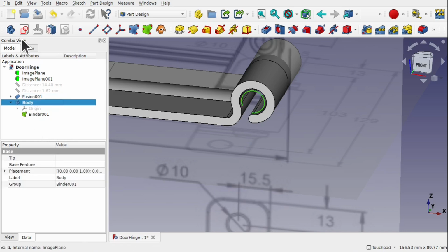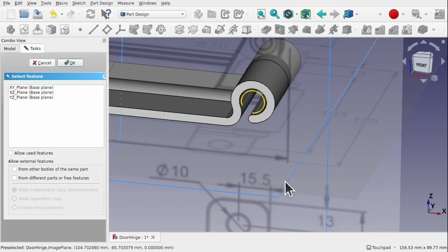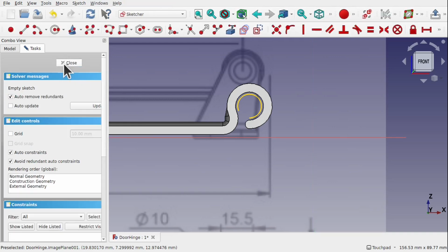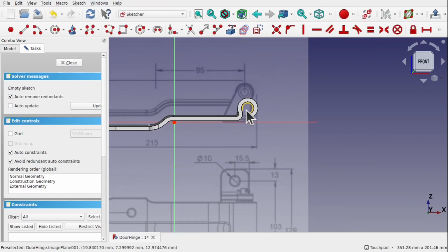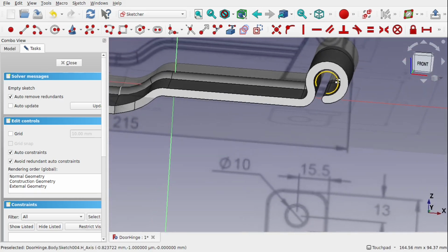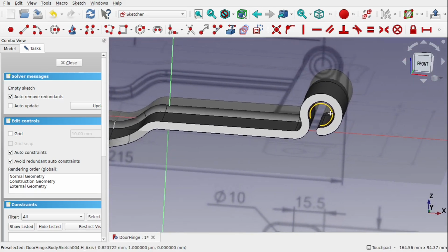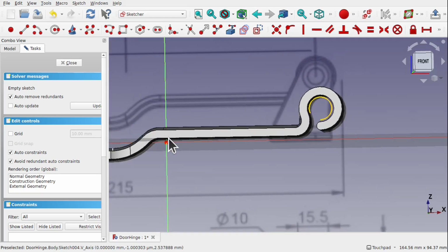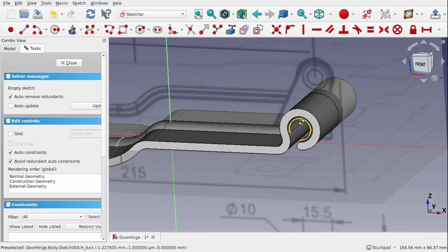So let's click on the body and create a sketch, and we want it along the XZ plane. So going from the front and select XZ plane, hit OK. Now we can pull in that geometry. We are away from the point of origin, this point here, which is fine. We're going to bring these together in, say, an assembly and export them as an STL, or export out the individual parts. If we want to do, we can move these to the center of origin. So when we right click and transform, our handler will be, say, in the center of here. But I'm just going to go for this for the time being.